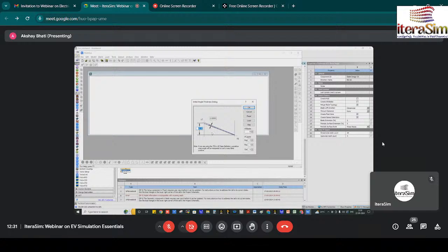But if you are developing a fan of metal, you need not consider more thickness, because it will increase cost, as it will develop a thicker fan. But we don't need that. Also, if we increase the thickness of the fan, the drag or friction on the fan will increase. So sometimes, on increasing the thickness, after some time it will degrade the fan performance. So we also need to consider the fan blade thickness carefully.